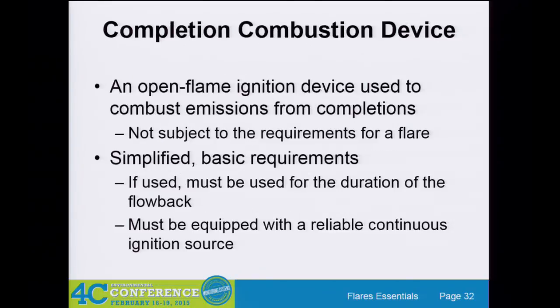Okay, completion combustion device. That's a definition written into the rule. I enjoy it because it specifically says a completion combustion device is not a flare. So why did they do that? They were trying to make sure folks controlled their emissions with 95% destruction efficiency and weren't overly concerned about compliance with 60.18.